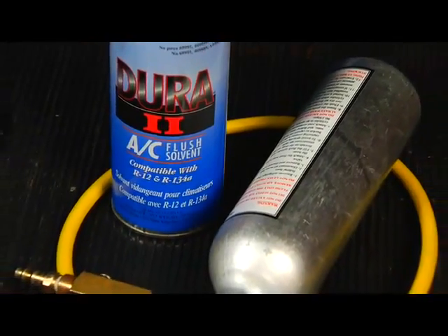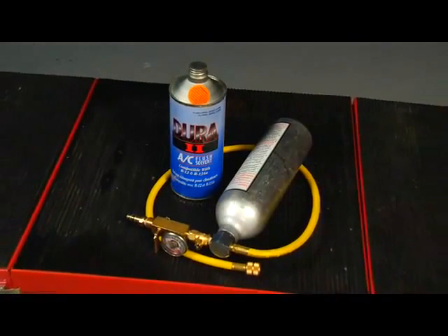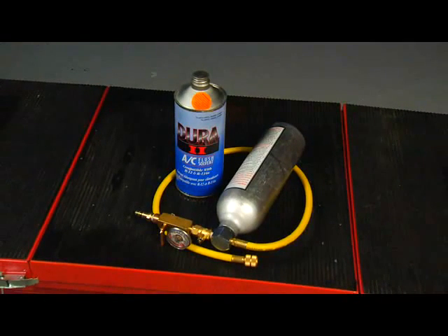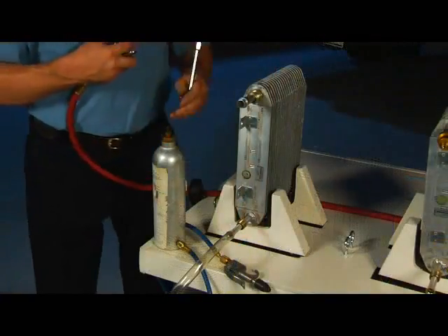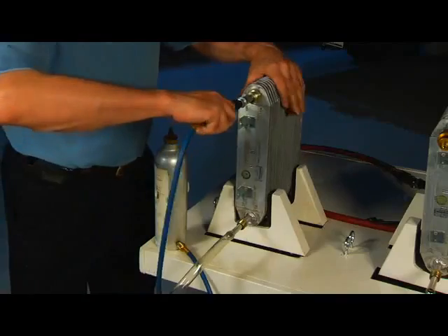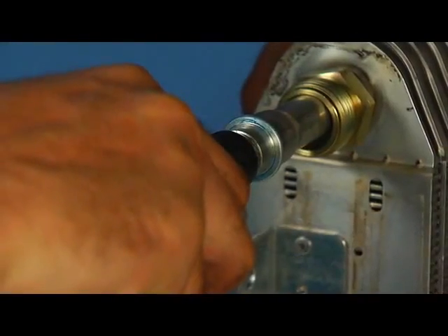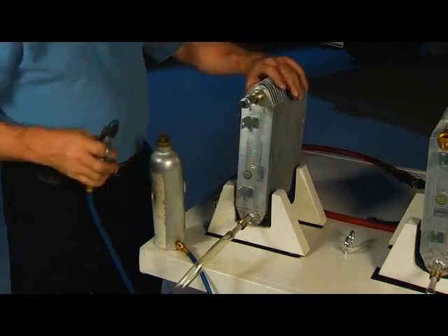The most popular AC cleaning tool is the flushing bottle and spray nozzle. If this tool is used incorrectly, dirty oil and solvent can be trapped in the evaporator. The standard flushing bottle is designed to be pressurized with shop air after the bottle is filled with the solvent. The technician would then disperse the solvent into the component via the spray nozzle. As the tank is emptied and the pressure drops, the solvent quits flowing.